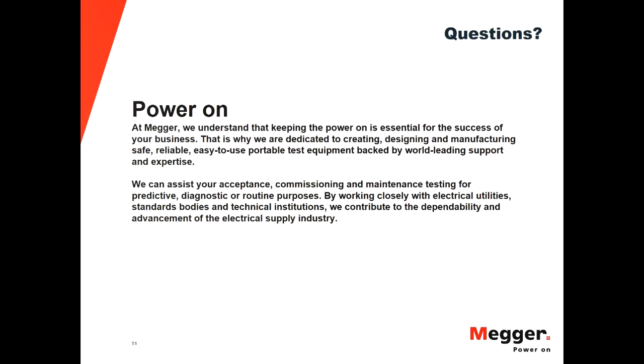All right, what is your opinion of conductance testing versus capacity testing? So when we talk about conductance testing in the standards or the guides, the term ohmic testing is used, and there are different ways of doing ohmic testing. What we promote is impedance testing, though there's also conductance testing or resistance testing done.